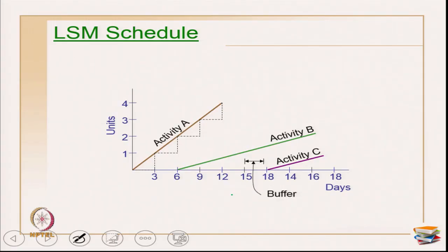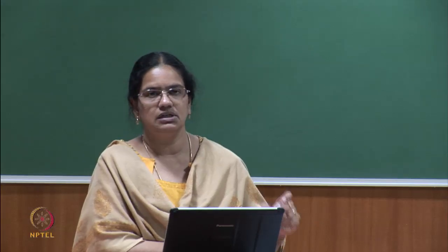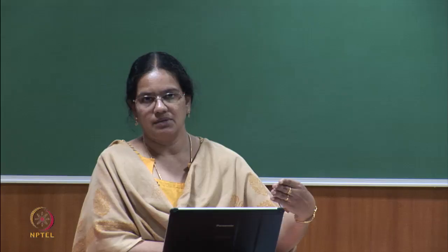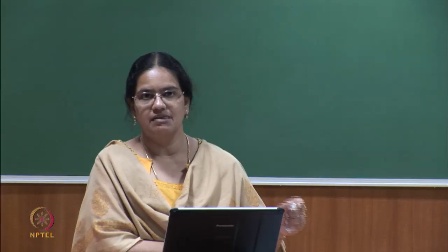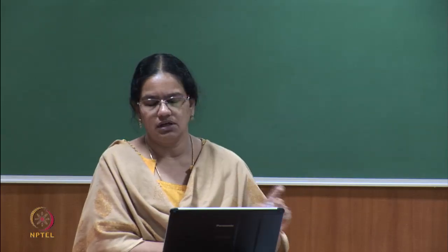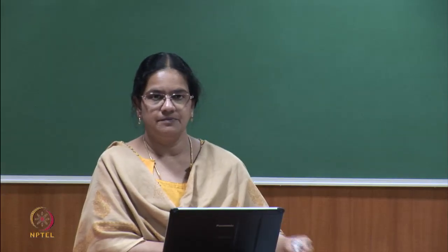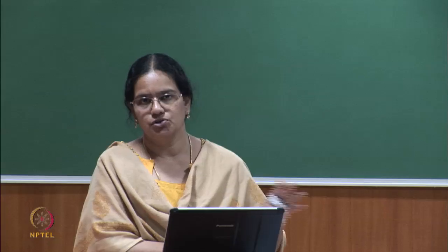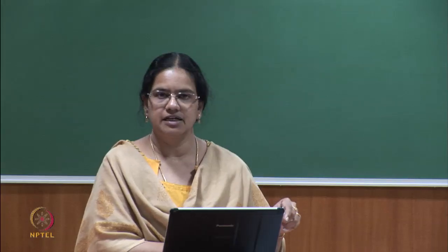Okay. Next is LSM. LSM is linear scheduling method. In the regular class, I explained to you the line of balance method. In line of balance, you know, primarily you have to draw two bars in order to show the start of the segment and finish of the segment. There is nothing called early and late, okay, which shows start of unit 1, finish of unit 1. So, it shows as a rectangular bar and the entire progress till the last unit is seen here.